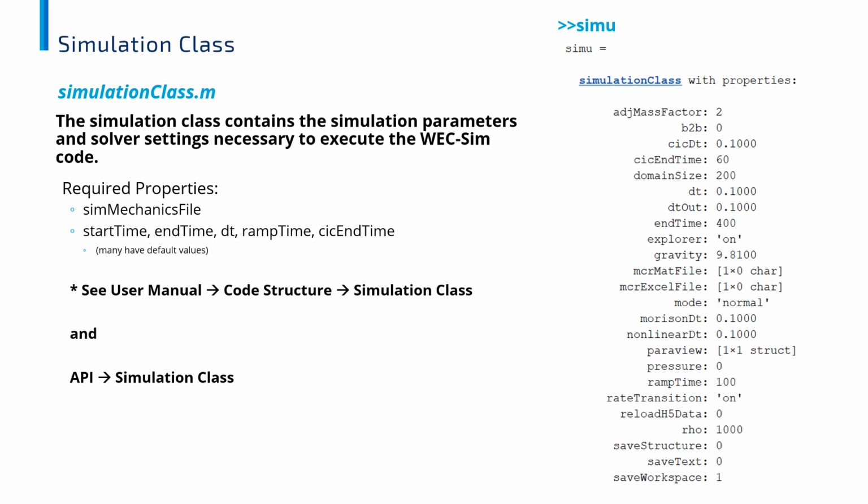However, it at minimum requires a SimMechanics file, that's the Simulink model you'd wish to execute, a simulation start time, end time, and time step, as well as a ramp time, that's the time over which the wave force is ramped up from 0 to its maximum value, and the CIC end time, which is the length of time over which a convolution integral, which theoretically continues to infinity, will be calculated.